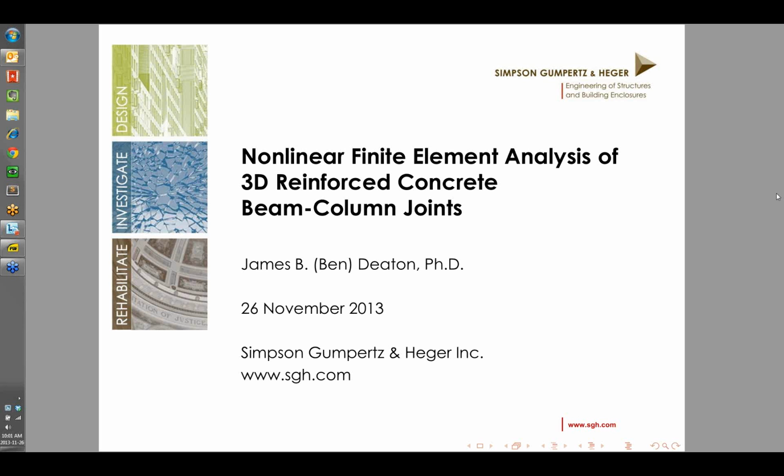So one of the questions was, how sensitive was the analysis to the mesh step? Did you have any specific criteria for selecting the mesh step? And what I can say about this was that this was really just a process of trial and error. So for especially the earlier studies, I did some parameter studies where I attempted a much finer step size in the solution control versus broader ones.